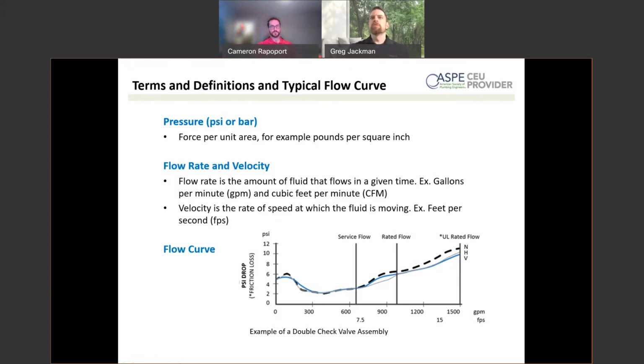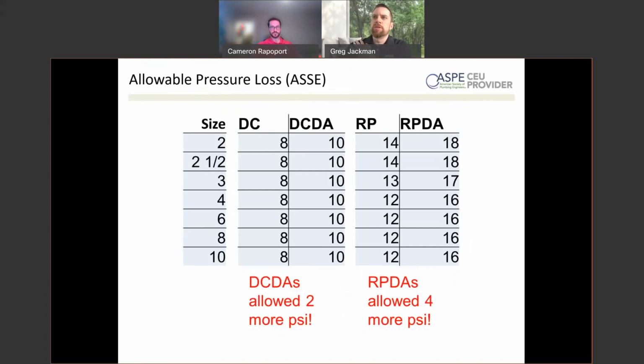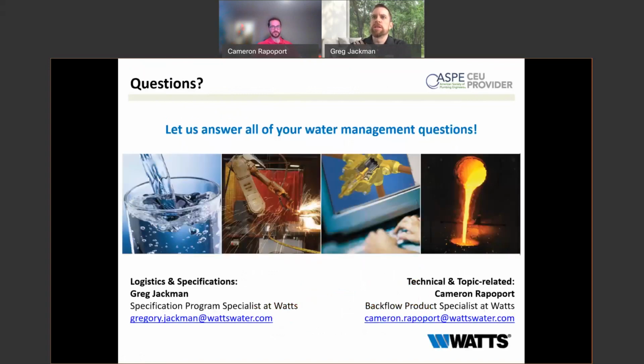Okay, if you have to make a repair on a backflow prevention device, possibly at a gym, where under current circumstances there's nobody on site and there's a possibility of draining the fire system, what precautions should you take? There's no one on site. There's a possibility of draining the fire system. I would talk to the local fire officials. Because if you have to make a repair and there's a potential that the fire system is going to be inoperable for a long period of time, they might want you to get a fire watch.